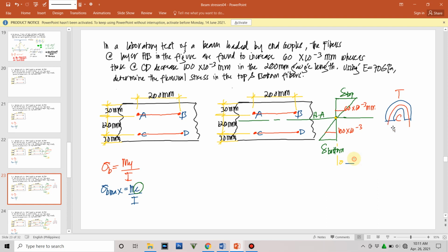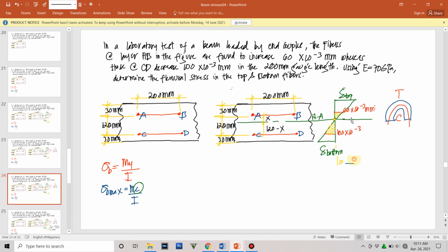So with this condition, of course, we can say that the fiber is concaving downwards because the upper portion will be stretched and the lower portion will be compressed, and that is what is given here. Now this is compressed because again this is a decrease, and this one has lengthened because this is a positive value. Now this is the zero deformation. This is positive and that is negative.